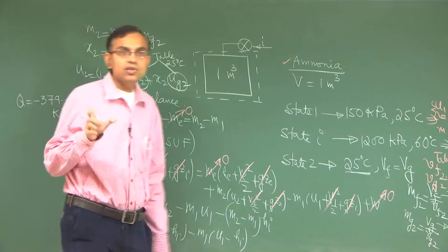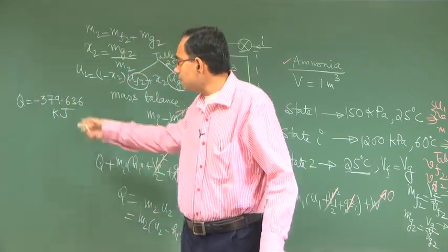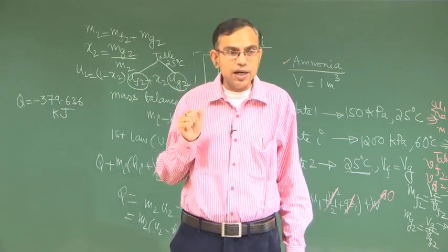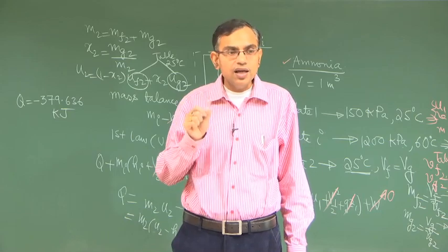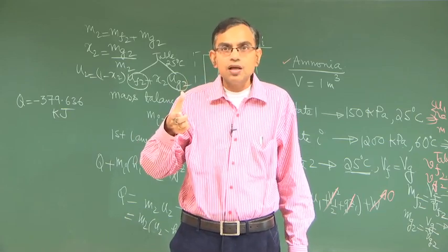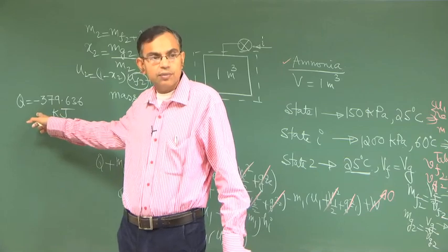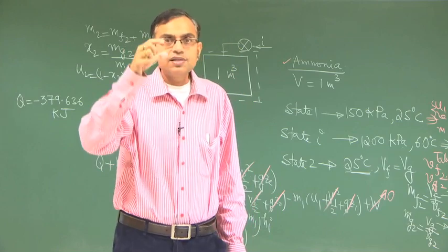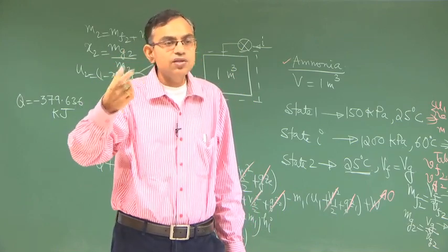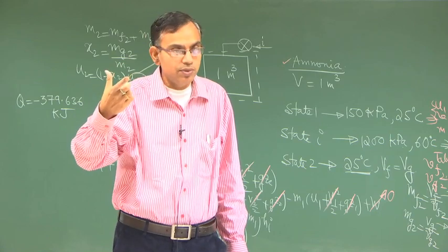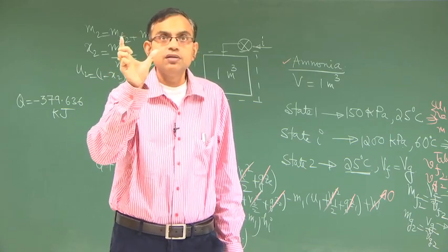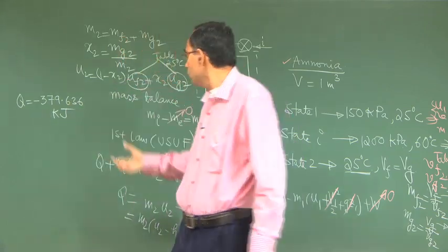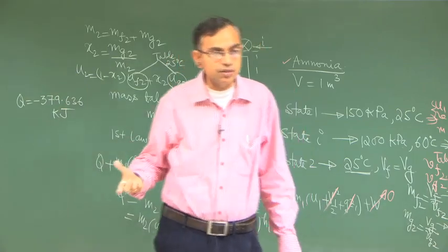So, all these are very important. So, why you can say that well the answer is coming negative, so I understand this. Why is this understanding required? This understanding is required because say you are solving a problem, and somehow the sign of this has not come correctly. That will give you a first check that the sign of either heat or work is not coming consistent with the physics of the problem. That should give you an alert. If you do not get that alert, that means you are just putting values and whatever is coming you are accepting it.